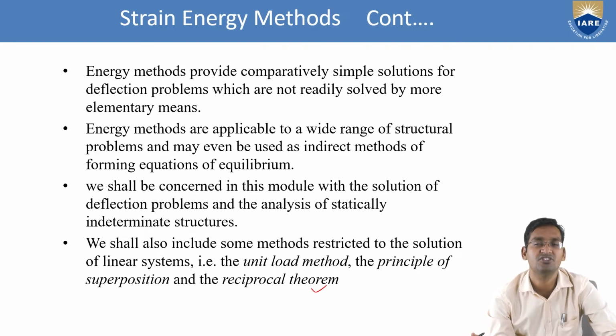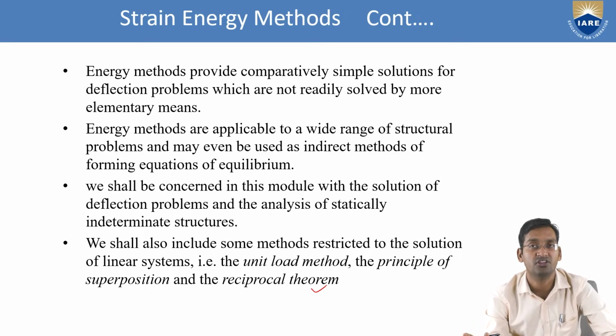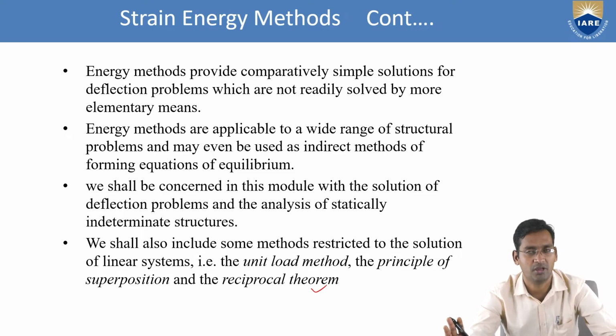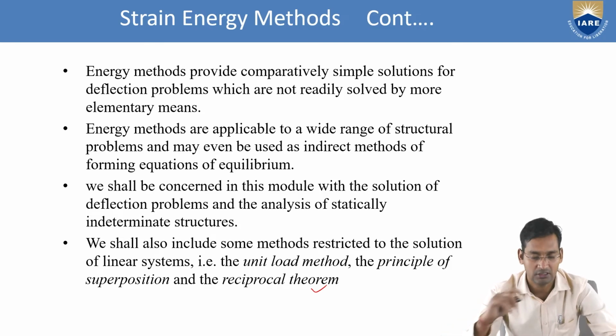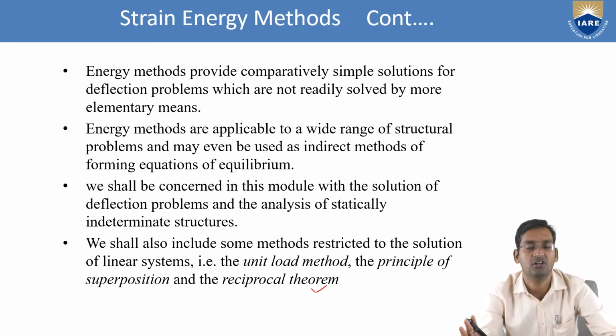If we change the load, the strain energy will still be equal to the complementary energy. If the deflection is different, the complementary energy will still be equal to the strain energy. So by varying either one, the complementary energy remains equal to the strain energy. Hence, we can find the complementary energy, use it as the strain energy, and by that find the deflection or load acting on that member.